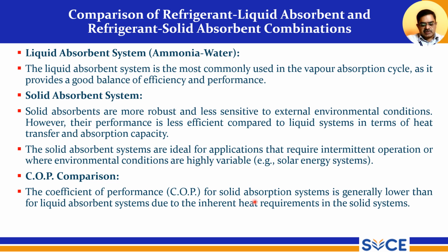So this is another important point. The coefficient of performance for solid absorption system is generally lower than the liquid absorbent system due to the inherent heat requirements in the solid system. So the solid system provides lesser COP because of the inherent heat that is there in the solid.